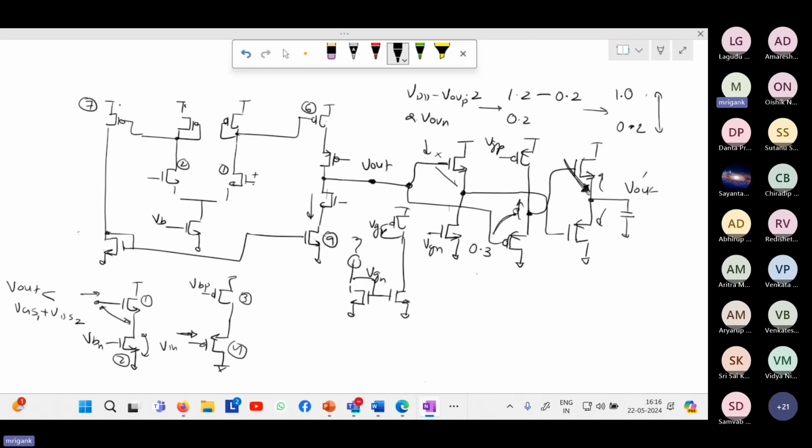In this case, of course, the PMOS current is not constant. It is going to vary. For example, if your voltage here is too low, the current here is increasing, the bias current will be increasing. And that may increase the power consumption, but it will make it closer to an ideal buffer.